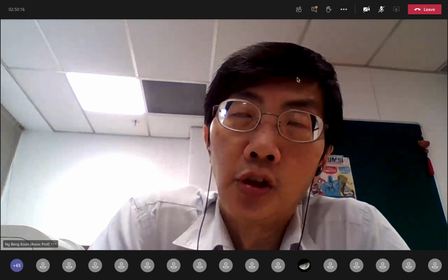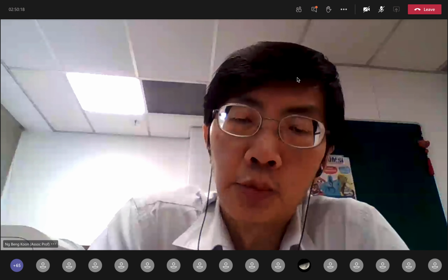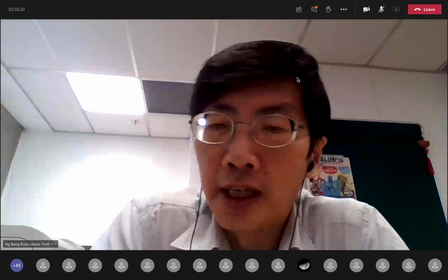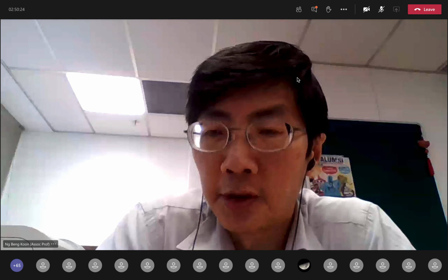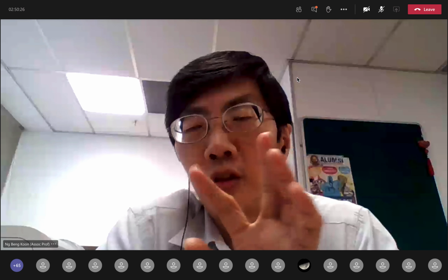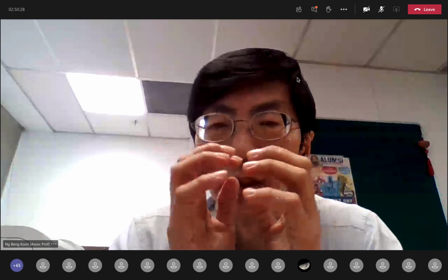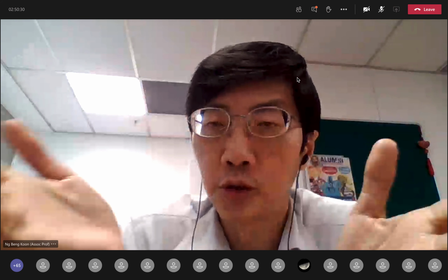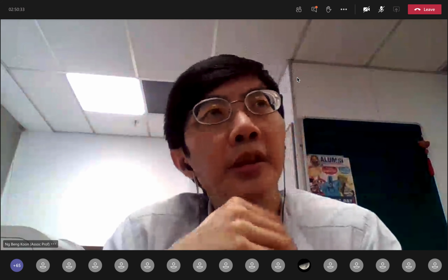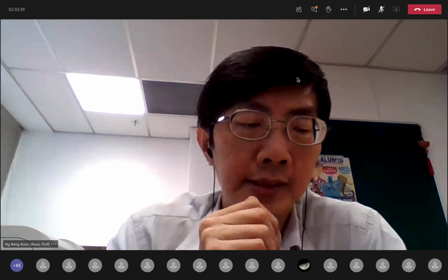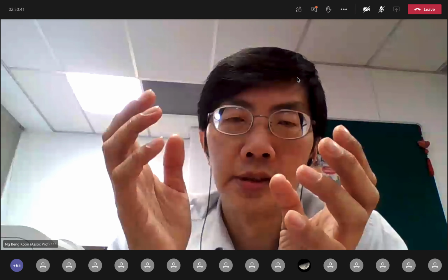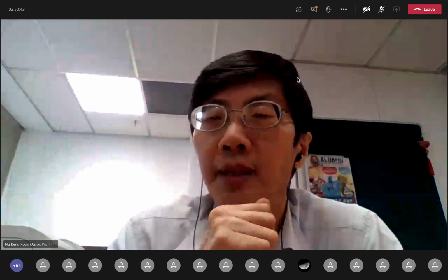Okay, so the indium and gallium are group 3 elements, and what you find is that depending on their ratio, their proportions in the semiconductor, you will have them in alternating positions. So essentially, they'll be uniformly distributed throughout the crystal. But in terms of the semiconductor behavior, it's largely the same as, or very similar to, a 2-element compound semiconductor.